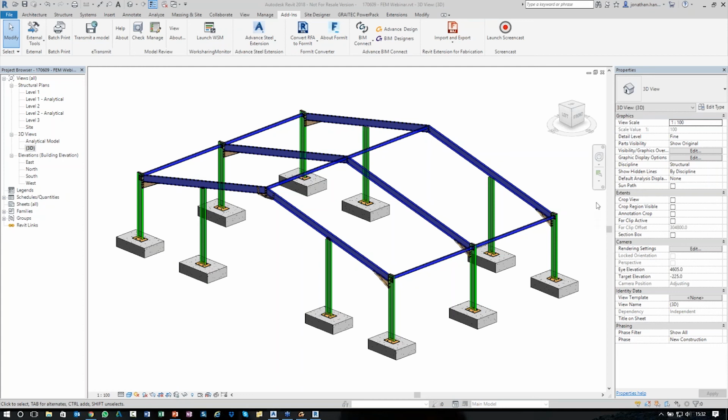Is it possible to have the same workflow with Tekla? It obviously is not as streamlined because this is all working upon Autodesk technology. So obviously the link from Revit to Advanced Steel is bi-directional, sequential. The link out with Advanced Design is pretty good. Obviously we're an Autodesk developer on top. You will need to check. I don't have much experience with Tekla, but I do know that they can export through IFC to Revit, but I'm not sure they will have the connection interoperability that you've just seen.